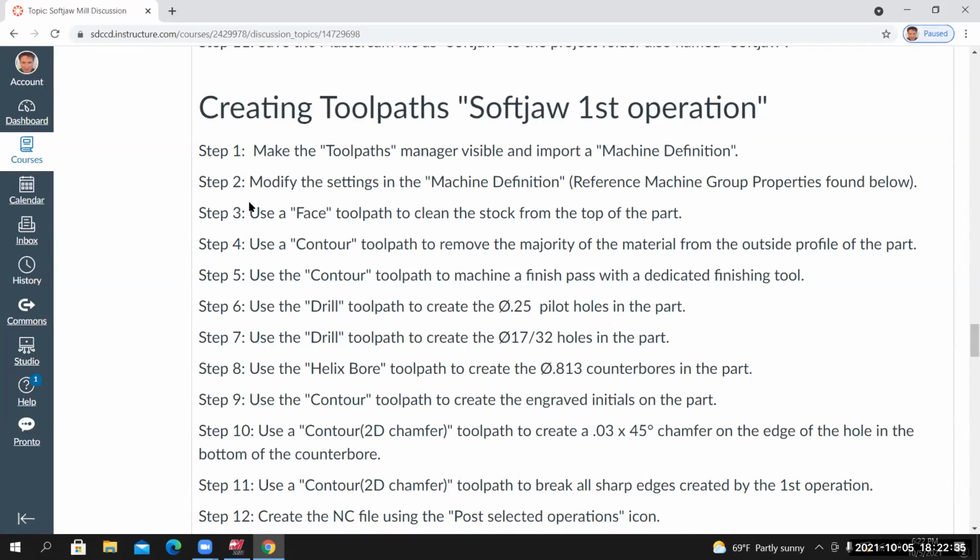Before we create any toolpaths, I like to create a stock model. Stock models will reside in the toolpath manager. We're going to create a stock model that represents the material before we did any machining to it. And we're going to use that solid model that represents our material to define that. So we're going to actually have 3 representations of our material floating around inside of this session of the Mastercam. One's used for verify. One will be a stock model that we're going to see inside of the toolpath manager. Then the other one's a solid model that the other 2 are dependent on.